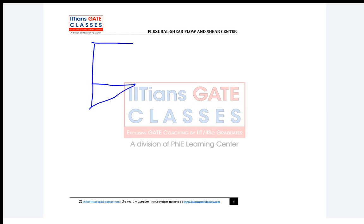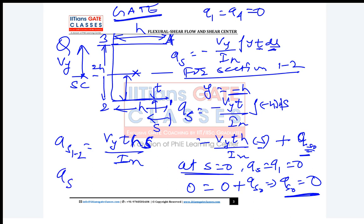Where will it be maximum? At 2. So if you find Qs2, at point 2, what is the s value? s will become h. So if you substitute s equal to h, Qs2 will be Vy t h square upon Ix. So you can see here it is maximum and it is linear.